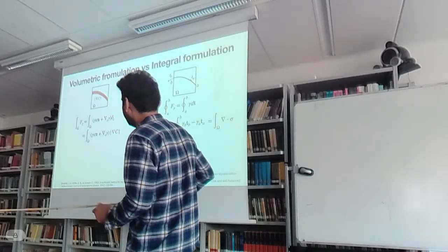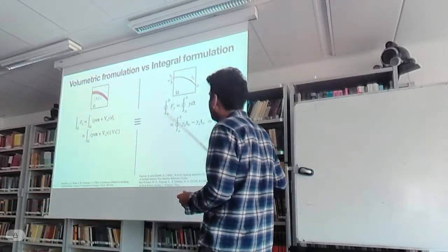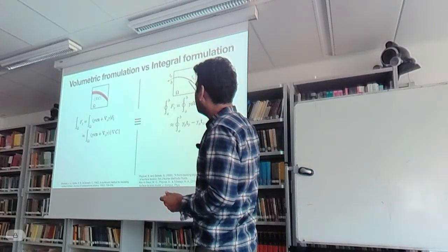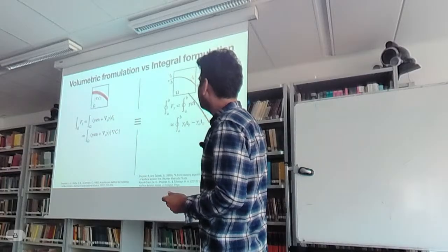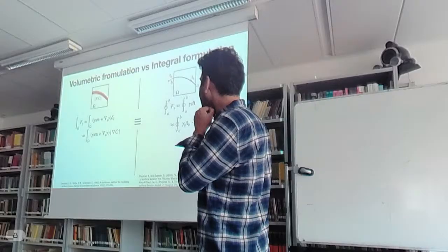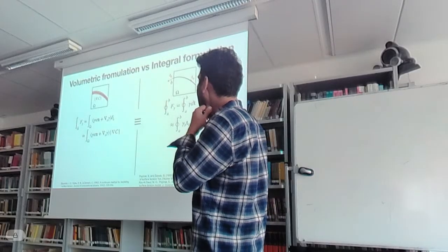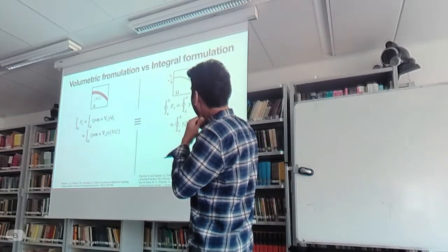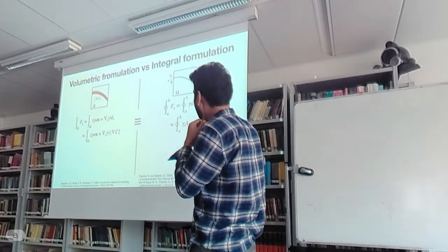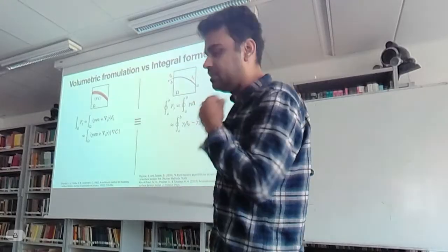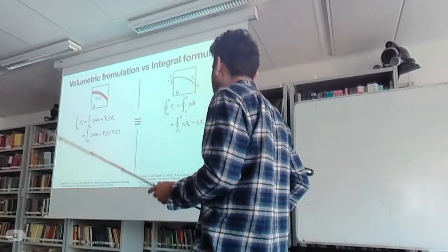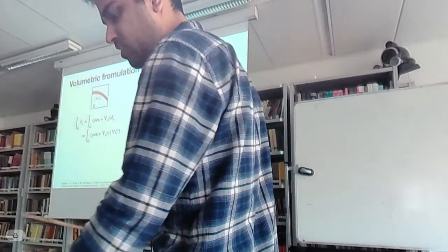This was proposed by Brackbill et al. And then the other idea is that you can represent surface tension as a line force, so you just need to integrate across the line. So it's sigma times dt, where t is the tangent vector, and what you need in discrete form is these tangent vectors at the edge of your control volume or the cell, and what is the surface tension constant there. And then you can add this to Navier-Stokes by using a continuum surface stress model.